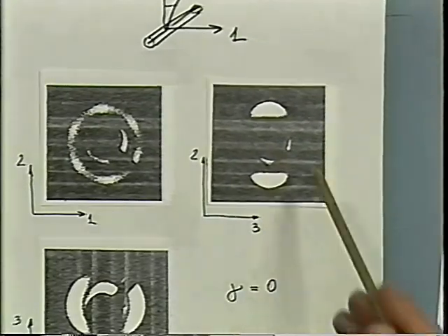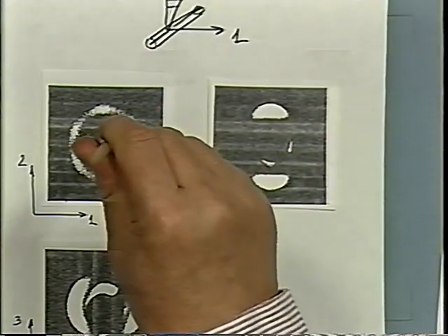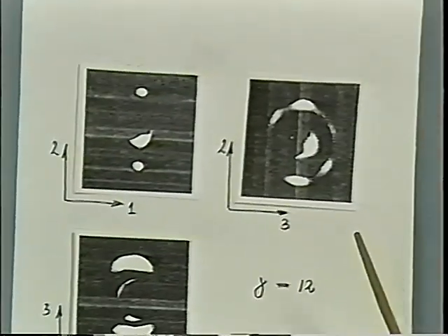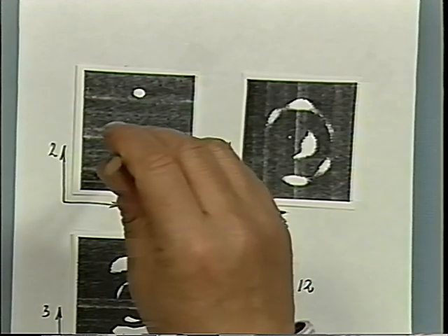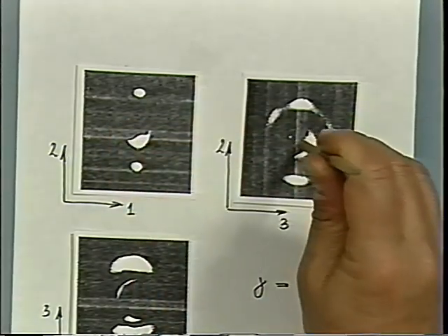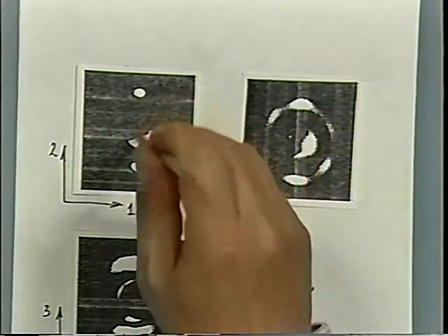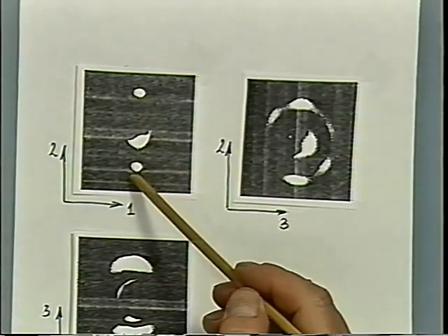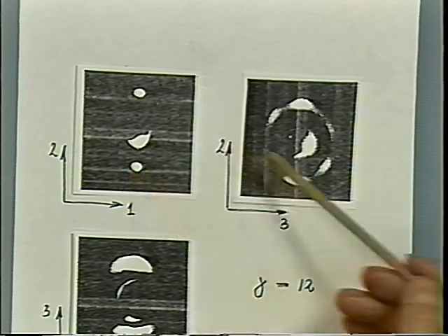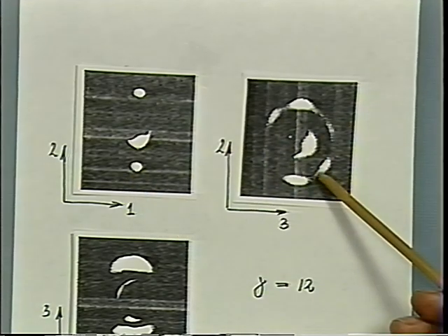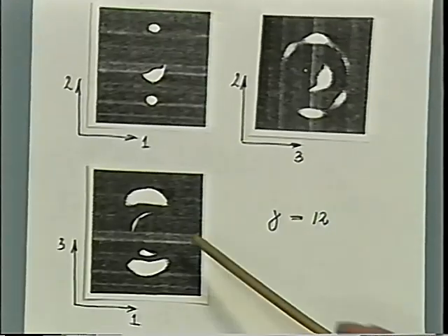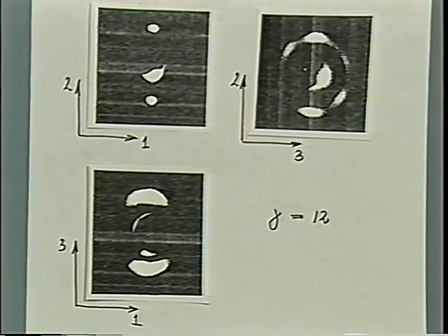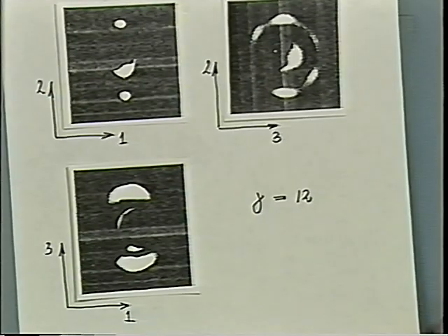We go from this initial structure where cylinders are aligned like this, and when looking from the side, have this alignment, to an aligned structure where the cylinders are aligned now when you look at the sample head-on, and those arcs are pretty sharp, so the initial cylinder orientation has been lost completely. We're really going completely to this new orientation. And looking sideways, it's not as perfect, but somehow shearing produces a very nice order, and we see that transition.